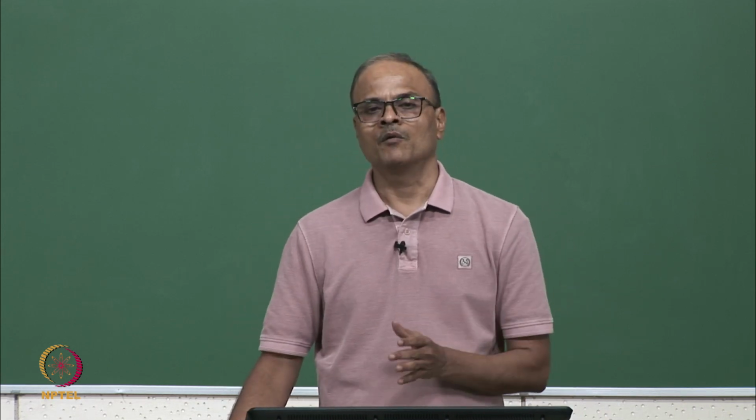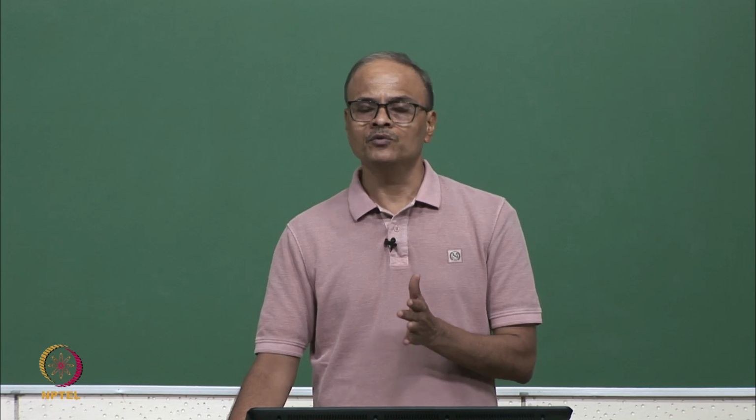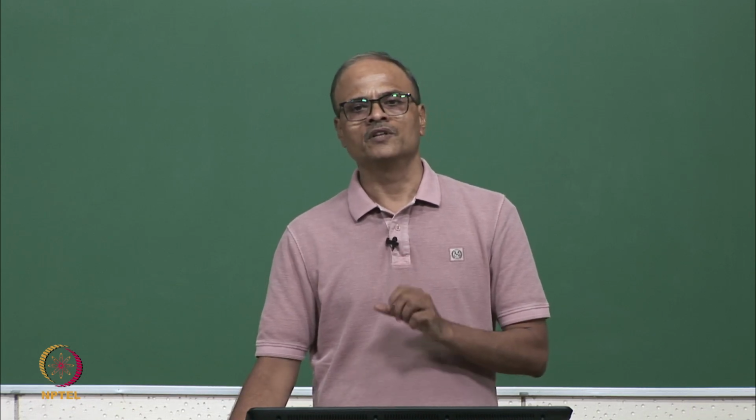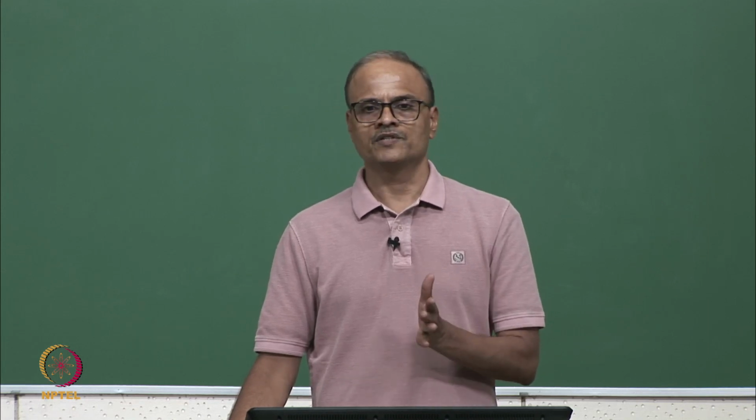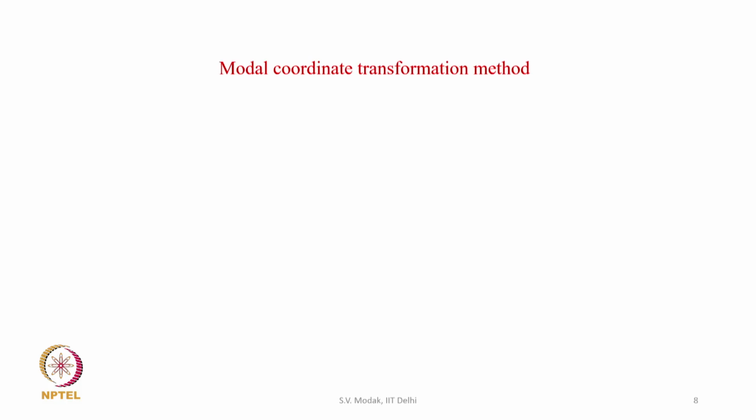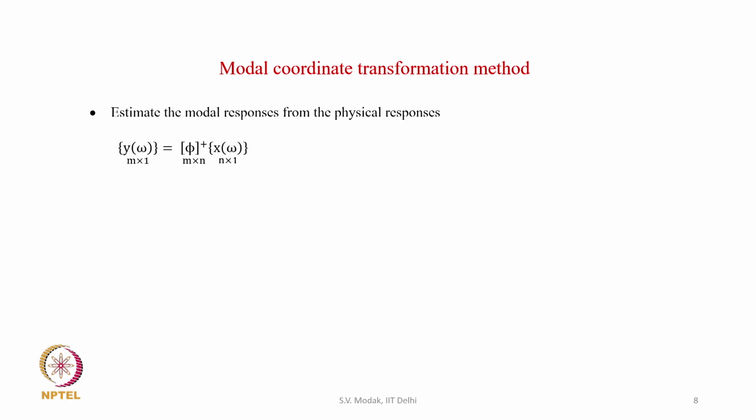So, approaches based on regularization techniques have been used and suggested in order to overcome this ill conditioning and obtain a more reasonable estimate of the forces at those frequencies. There is another method of force identification, and that is called the modal coordinate transformation method. It makes use of the modal model which is obtained from the measured FRFs.